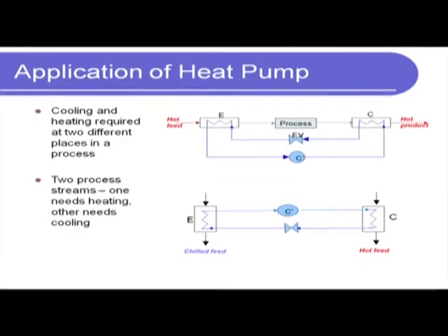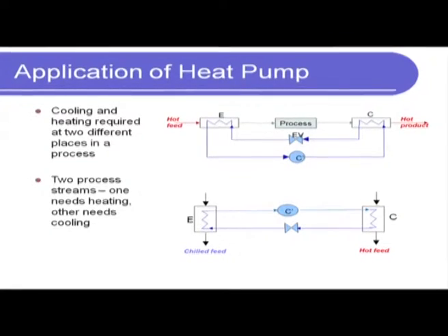and then it passes to the evaporator where it boils and becomes vapor, and as it boils and becomes vapor it extracts or absorbs heat, thereby cooling the ambient of the evaporator, right, and then it comes to the compressor and the cycle repeats.